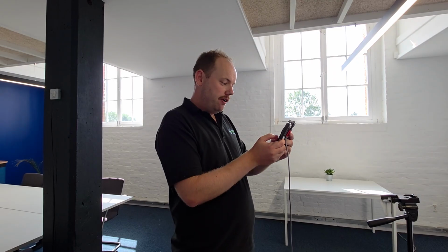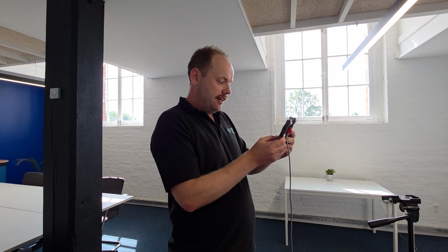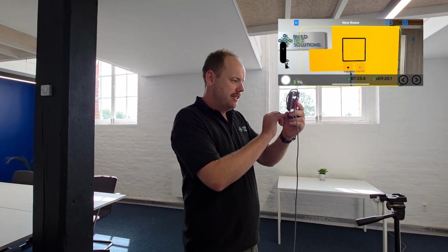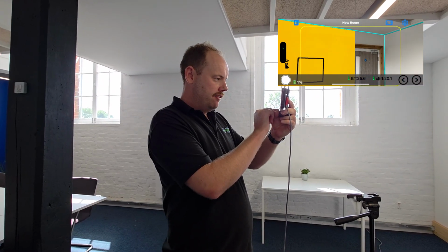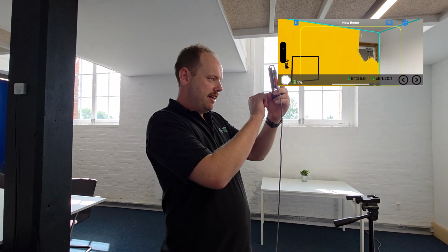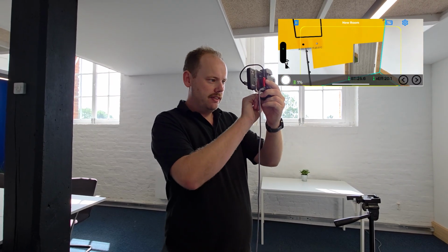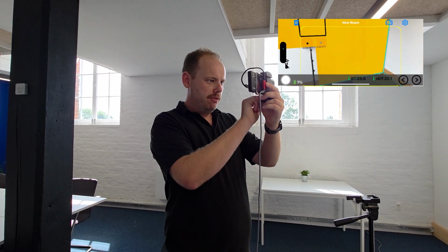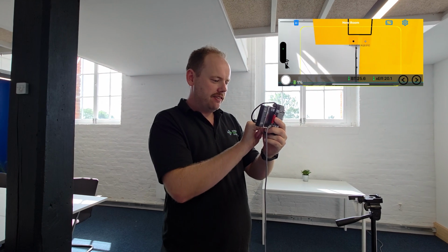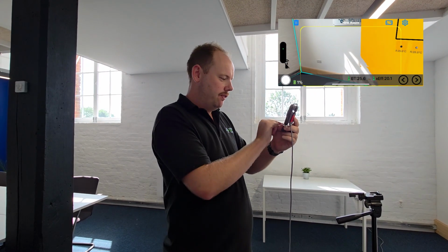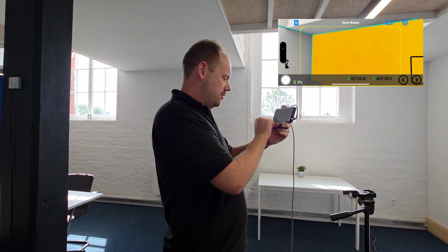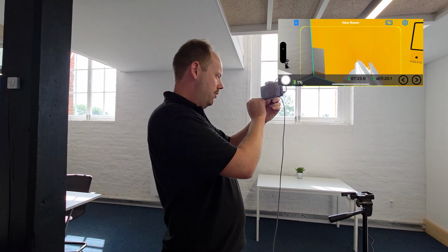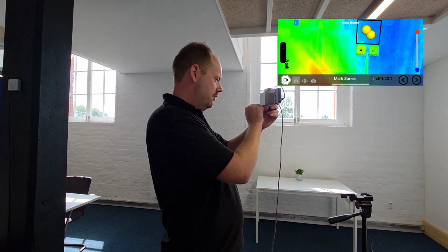So we press the arrow in the bottom right to say next, and now I'm ready to start taking my thermal images. I want to get my first thermal image including the targets, and then I can measure across the whole wall surface. You'll see it's pretty warm in here. It's actually the middle of summer and we're just giving a bit of a demo of how the equipment works. So I can do thermal images across the whole wall surface.